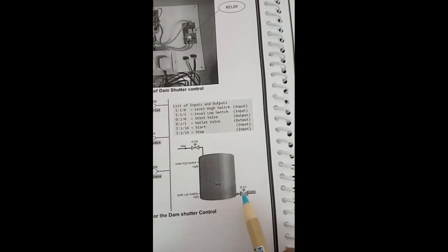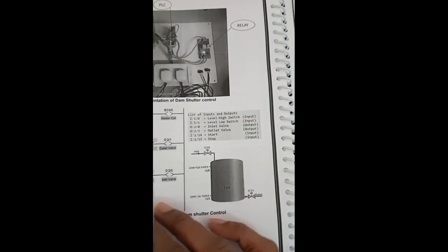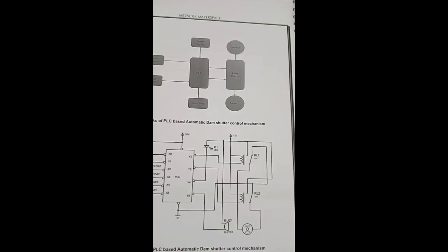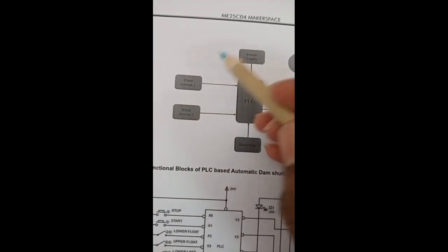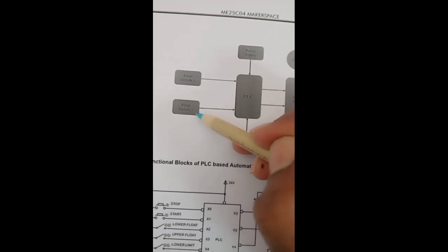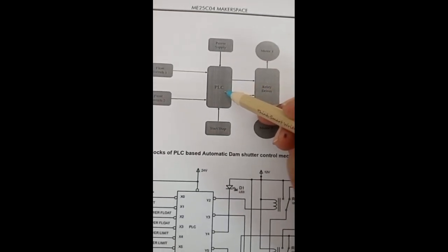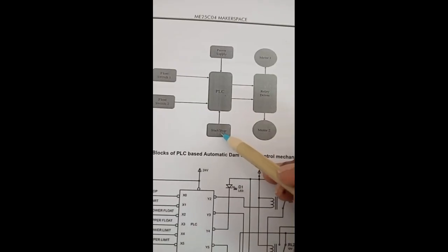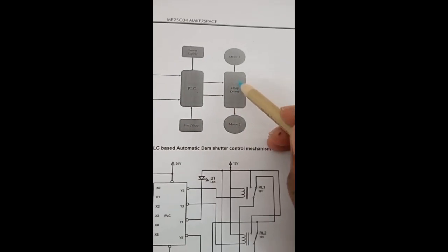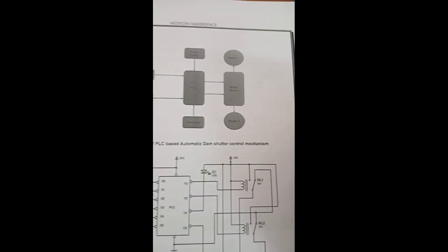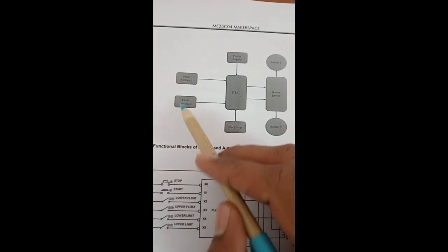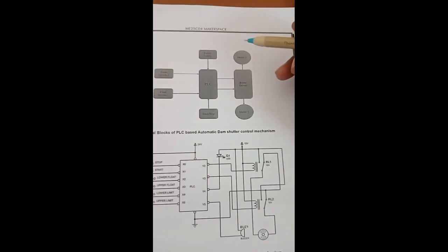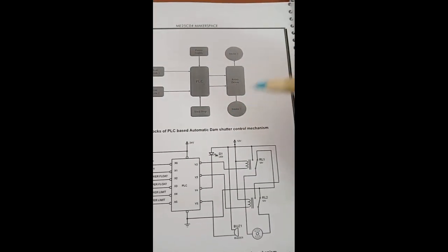This is actually a different setup. We have taken a dam that has a special structure, inbuilt with float switch 1 and float switch 2. A PLC is the master in this system, and there is a power supply for all the elements, a start and stop switch, relay drivers and motors. With the help of float switches, we can identify whether the water level is at the bottom or top of the dam.